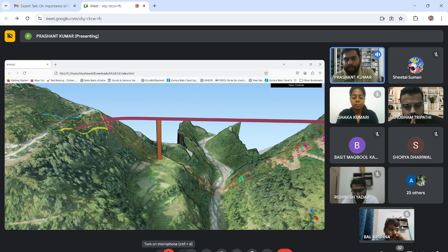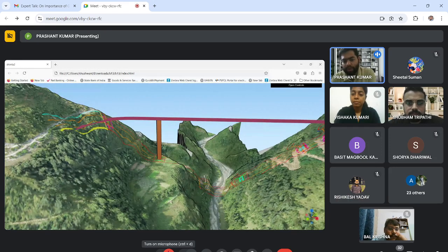The geotechnical consultants in our country currently don't use triple core barrel. That is a very major problem. If you have a triple core barrel, the core will be very fine. You can see the discontinuities and everything. The single core barrel deforms everything you are getting. So we also use RocLab because there you have to give the dip angle and everything, and it gives the GSI value. So it was a combination of software we used.